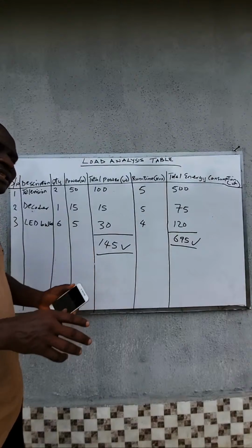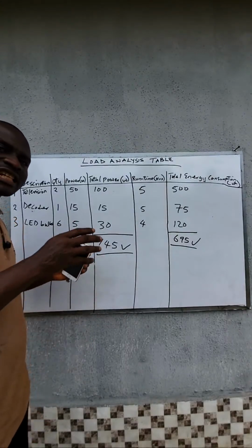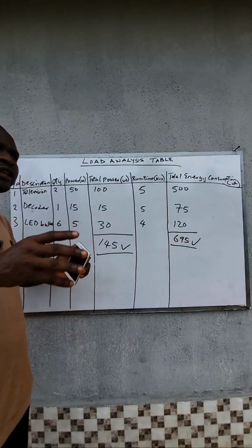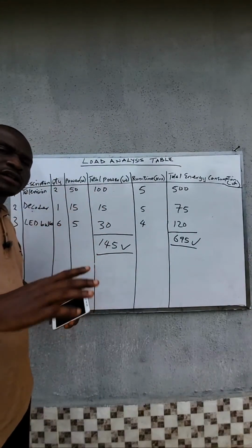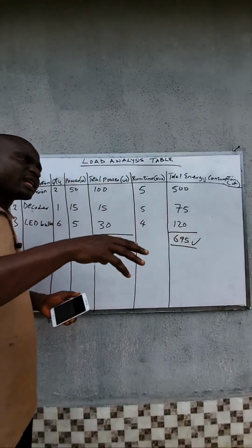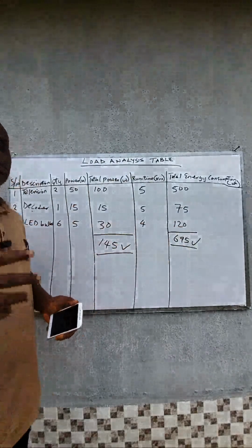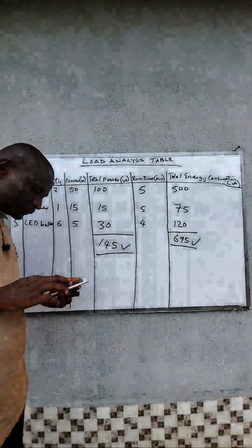So if you want to charge deep cycle batteries, there are chargers that are meant for that. If you use a charger that has constant charging, even when the battery is full, it will not detect that the battery is full to stop sending high current, high voltage to the battery. It will kill the cells of your batteries.